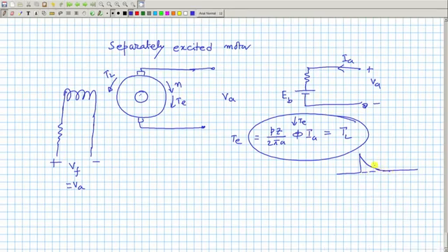If the machine is under absolutely no load, even with no eddy current and frictional losses, then the final armature current will be 0 and it will run at a constant speed without drawing any current. That means Eb, as speed was increasing, will become Va, so that no current is drawn.